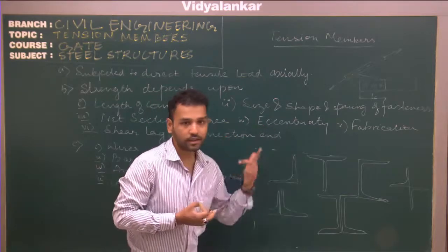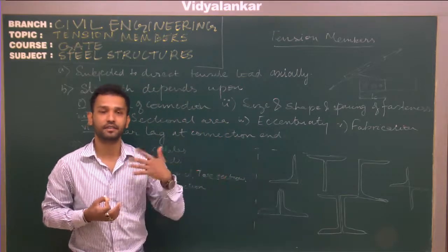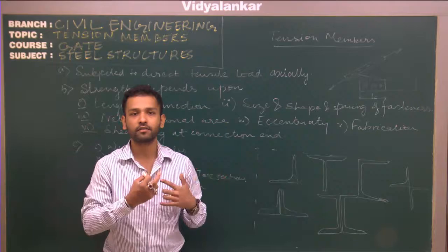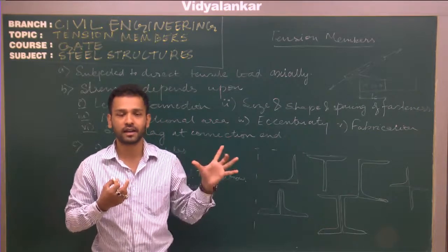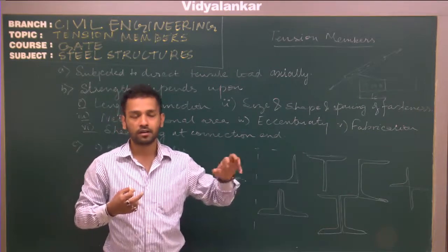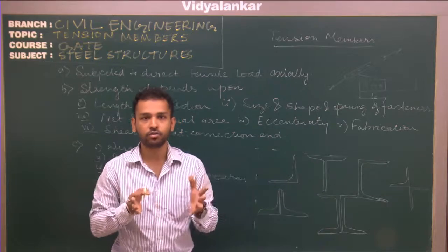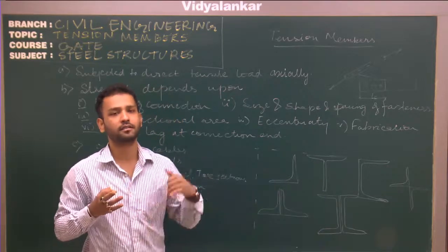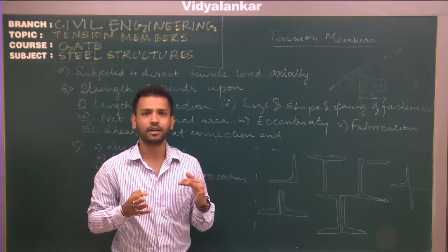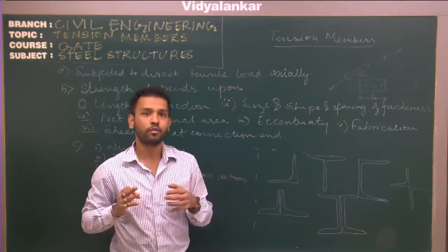Eccentricity. As we have seen in the bolting conditions also, if the eccentricity is high, then the impact of the loading will also be high, because the moment that is induced due to the eccentricity, either a bending moment or a torsional moment depending upon the plane of the loading, will be high.